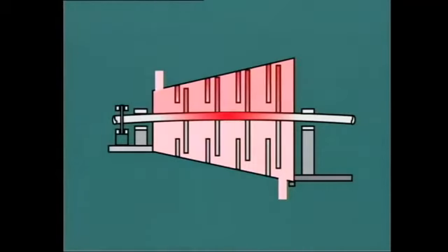When this occurs on the rotor, it leads to an increase in eccentricity. The shaft and rotor take on a slight bow due to temperature distortion, and this is exaggerated by the centrifugal force of rotation. Eccentricity is dangerous because it results in a reduction in radial clearance between the rotating and stationary parts.